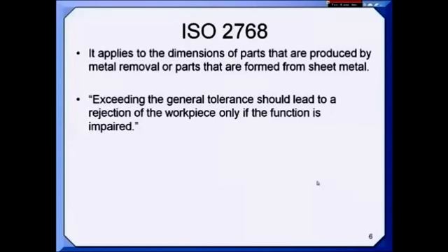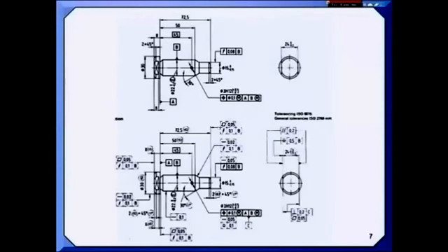In the standard, they show this sample drawing, a fairly simple drawing, and we're told that if you use the tables, the tolerances that are down here in phantom are implied. So all the stuff in phantom here is implied. On a complex drawing, I don't know how you'd be able to figure out what is implied on these features.